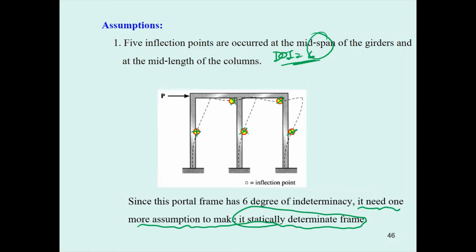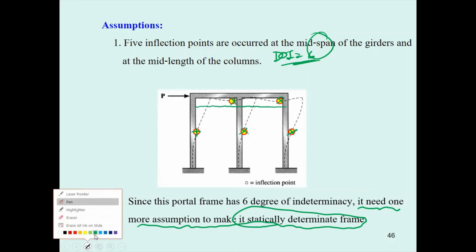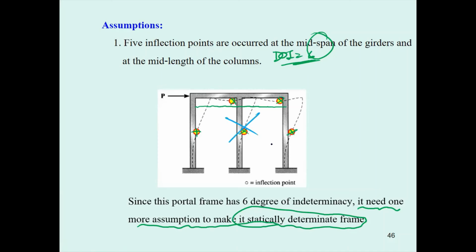One is the portal, one is the cantilever, and for this kind of low-rise building, the portal is going to be easier. Just set the shear force on the roof floor to be constant, and when the shear is constant, this column will take no axial force due to the applied load.